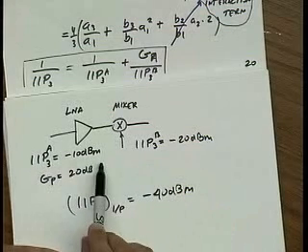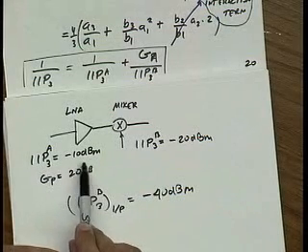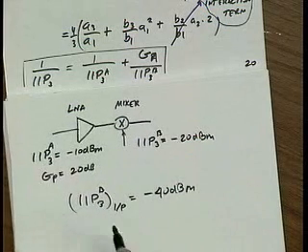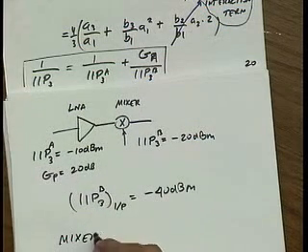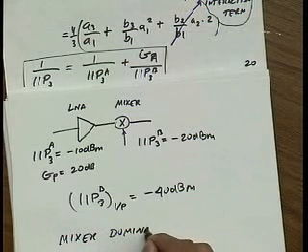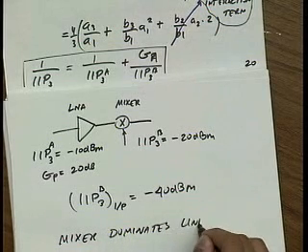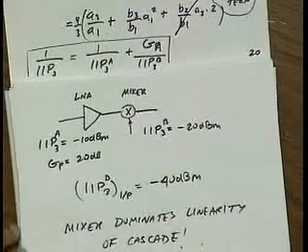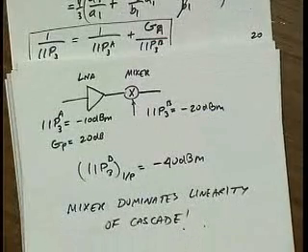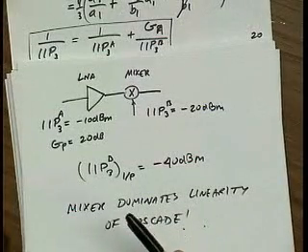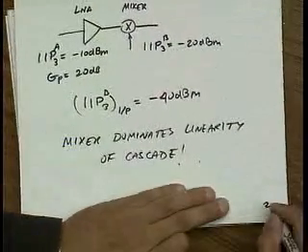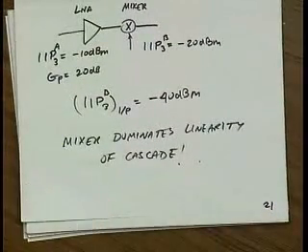So it's 10,000 times smaller than the IP3 of the input stage. So clearly, the mixer will dominate the linearity. There's no need to even use that formula because one term is 10,000 times bigger than the other term. Okay. Questions, comments?